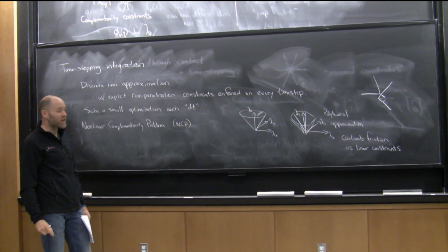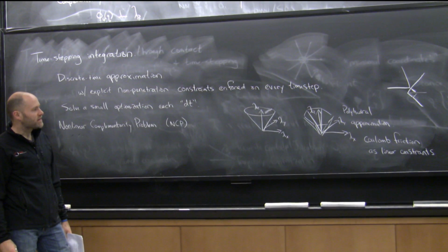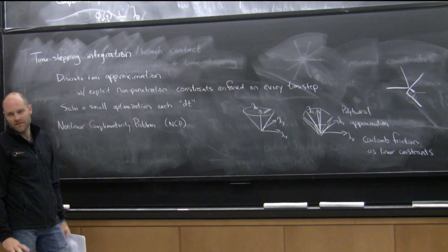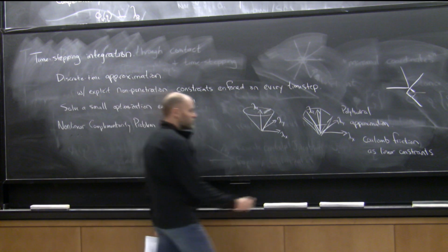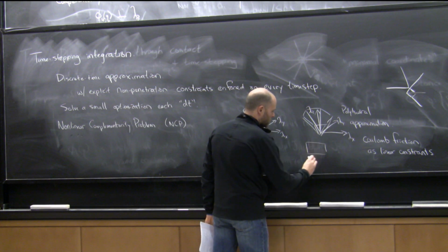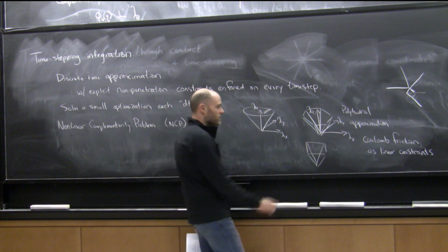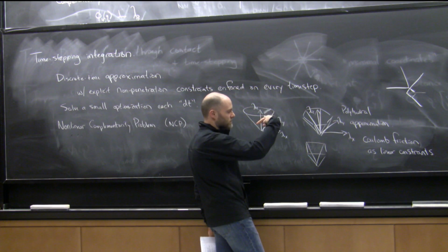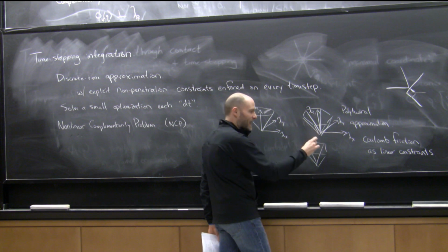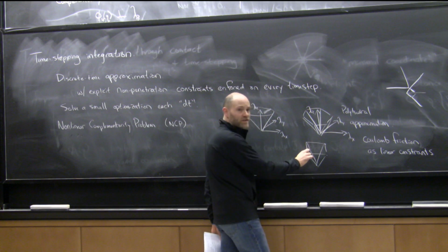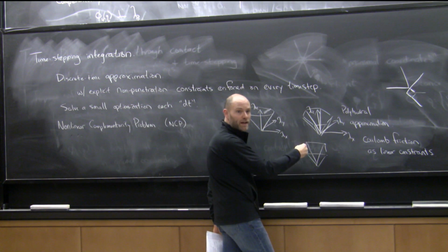There's some really subtle things that happen inside. Like that picture doesn't look so bad, right? If you start looking carefully at the way the solvers use it, it'll make you cringe. Like for instance, the maximum dissipation. So first of all, a lot of people just use 4, right? Just because that's super fast. But then maximal dissipation, the fact that the dot product of your sliding force and your velocity needs to be maximal, means that when you're sliding, you're only getting forces from one of those 4 corners. You'd like to feel like you'd get it from anywhere on the surface, but in practice you only get it at one of those 4 corners by maximal dissipation.